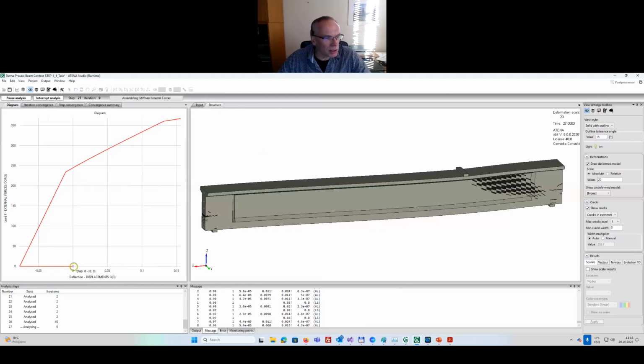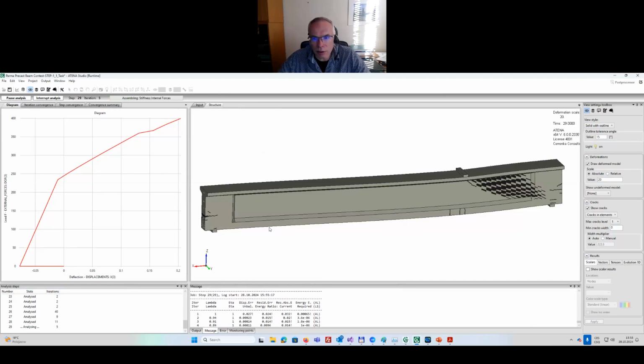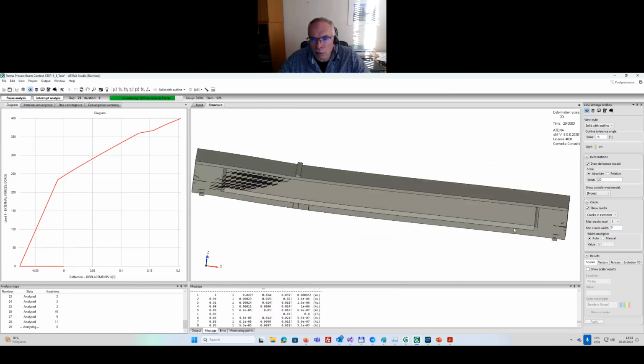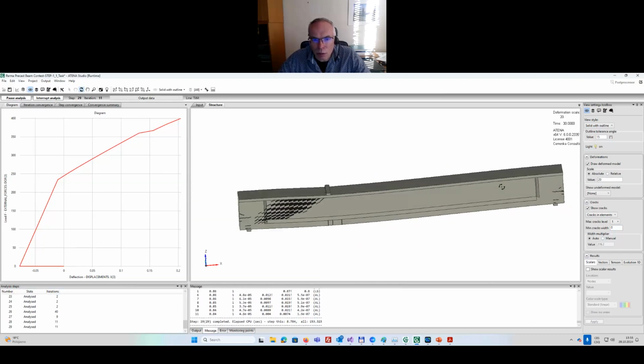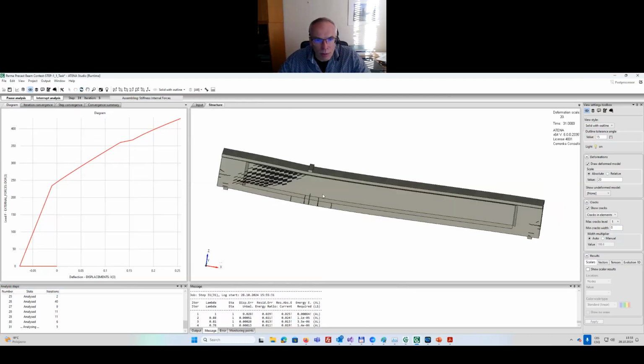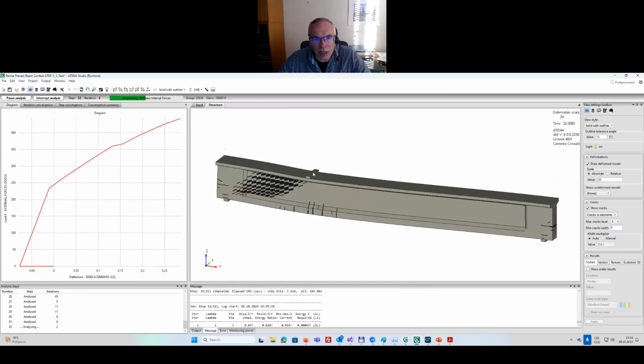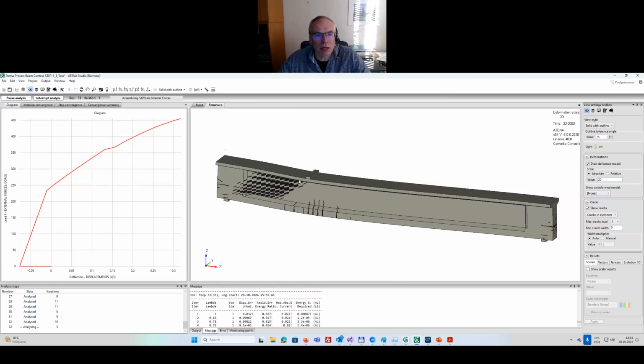First, we see that when we applied the pre-stressing, the deformation of the beam went upwards, and then we start applying the load at this loading plate. Maybe I'll rotate it a little bit so it is in the same way like it was in our preprocessor. There we had the x-axis pointing to the right. So we are applying the load here. This load is gradually increased up to failure. We see how the cracking propagates. So we have some bending cracks, also some shear cracks developing.